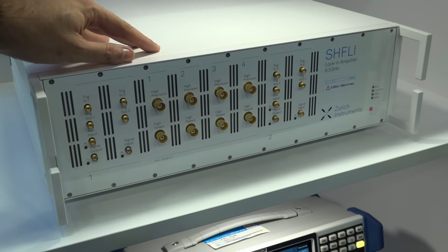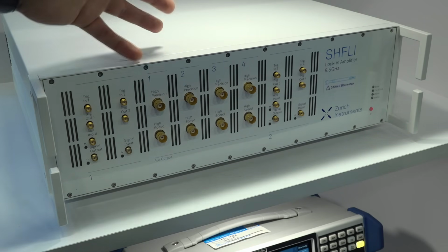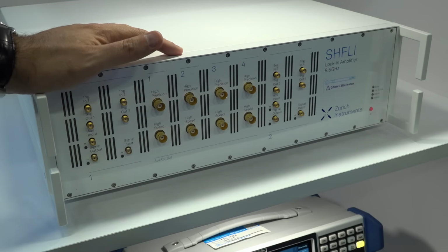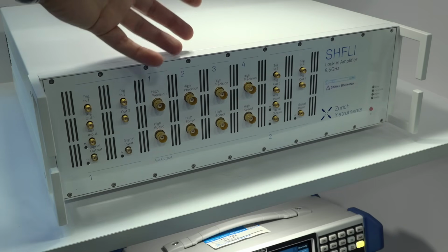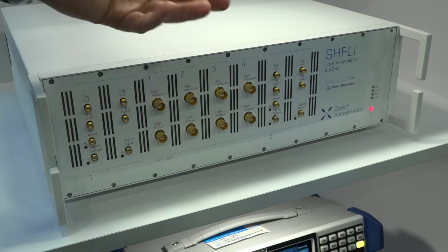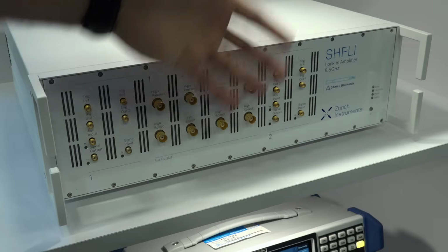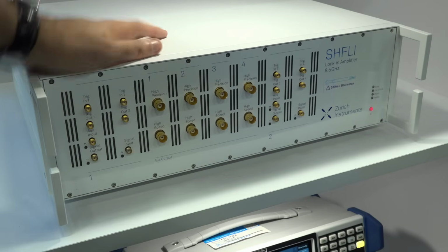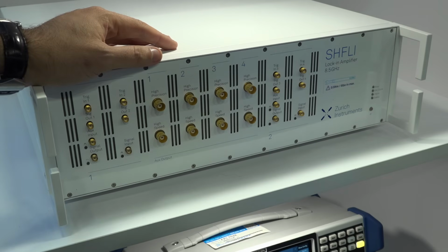But one key aspect is that if you want to do lock-in amplification up to 8.5 gigahertz, traditionally people would have had to build down converters and up converters in front of classical lock-in amplifiers. The challenge is you're just adding uncertainty to your measurements, and you're not getting any feedback on the saturation or the compression behavior of everything you've added to your system. This abstracts all of that away, bringing the measurement plane up to 8.5 gigahertz with all the demodulators and modulators to the front panel connectors. And that's a completely different system now, significantly reducing the time it takes to do these tests.